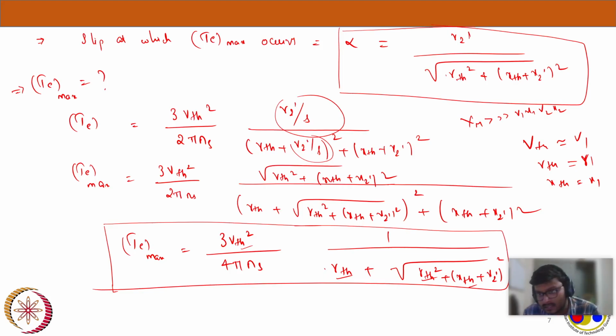Like last week we solved the problems of adding external resistance. So if you keep on adding external resistance at the rotor side, we have seen that last week the starting torque has improved, but your maximum torque does not change because it is independent of rotor resistance. Whatever the rotor resistance might be, you will have a fixed maximum torque at the machine.